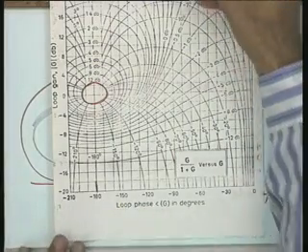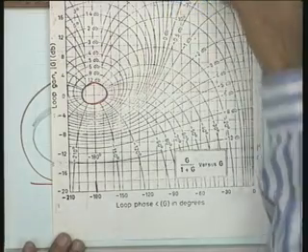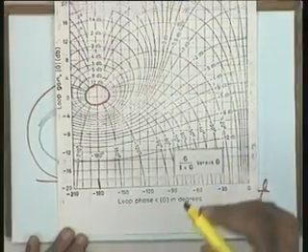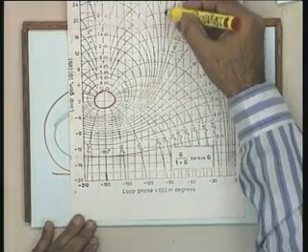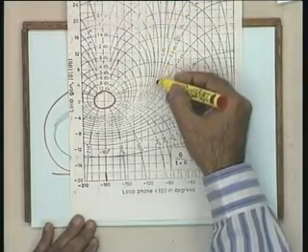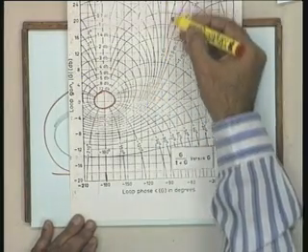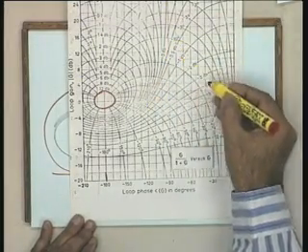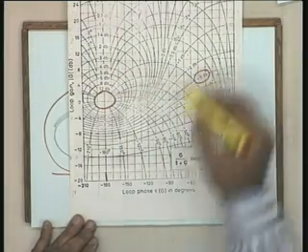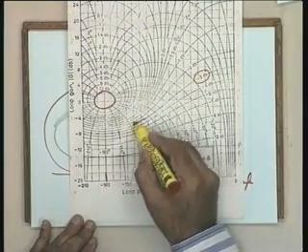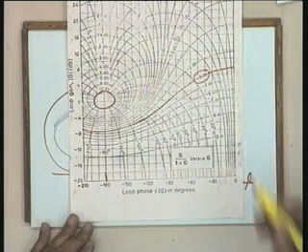Okay. Now, look at this, these are the different dBs. After 0.25 you come over here, and 0 dB, which corresponds to M equal to 1, is this curve, please, the 0 dB curve. This is 0 dB. I hope it is okay. Then after that you go to these values, and the dB which is again of extreme importance to you is minus 3 dB, which I will make darker. This is the contour corresponding to minus 3 dB.